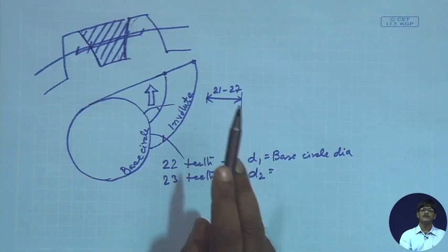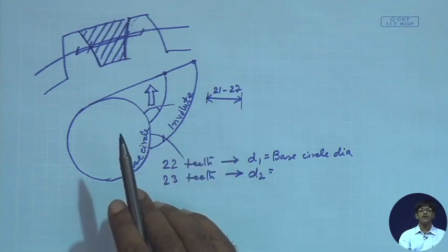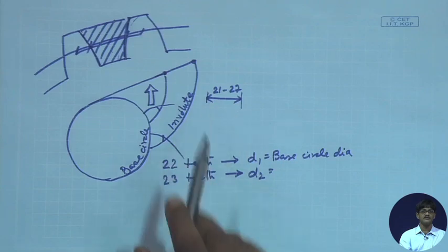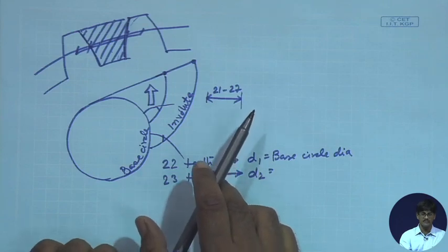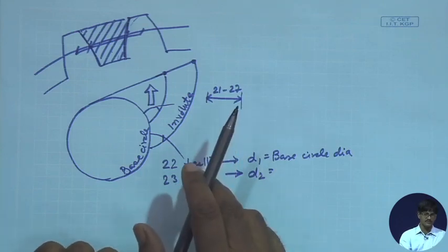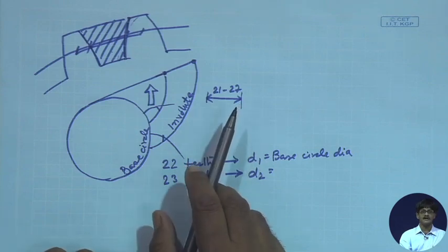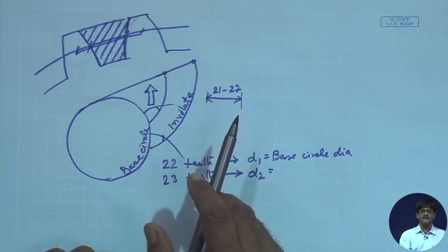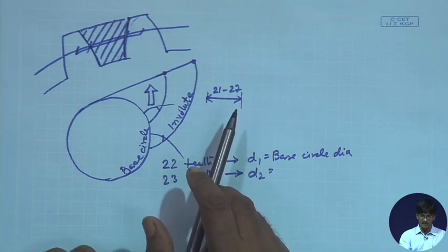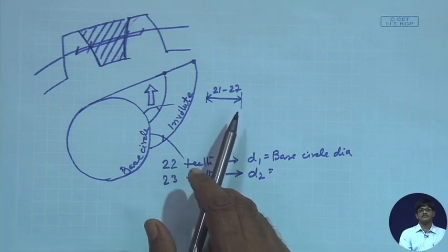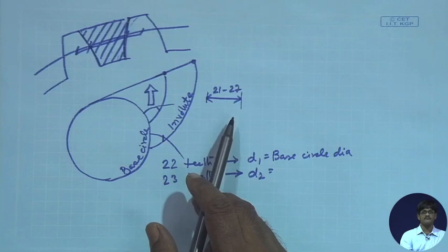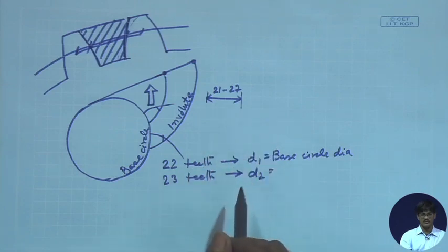What is the practical solution? You do not spend much money to cut all the numbers of teeth for gears belonging to a particular module. Just buy 8 cutters and that is it. You will be tolerating a definite amount of error, but that is tolerable. In engineering, tolerance is the idea by which ideal problems get practical solutions. So, we have this concept of cutter number, and a set of 8 cutters can tackle all the numbers of teeth belonging to a particular module.